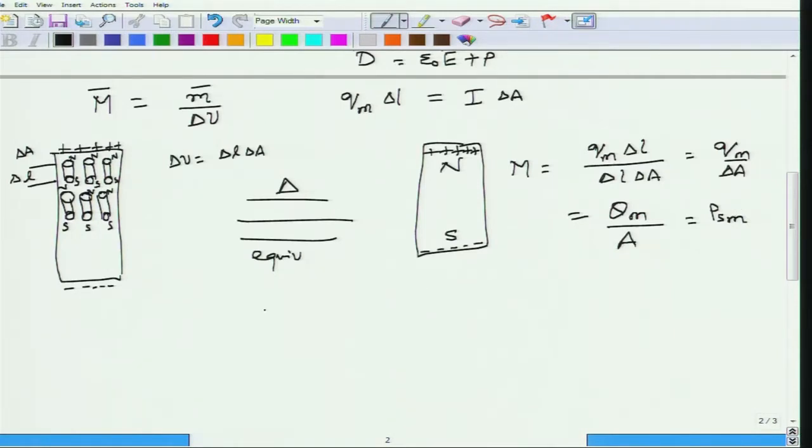So, if you look at the top and the bottom surfaces of the bar magnet, you would see them populated with magnetic charges with a magnetic charge density plus rho Sm, and the south pole is all populated with negative magnetic charges, or with a magnetic charge density of minus rho Sm.